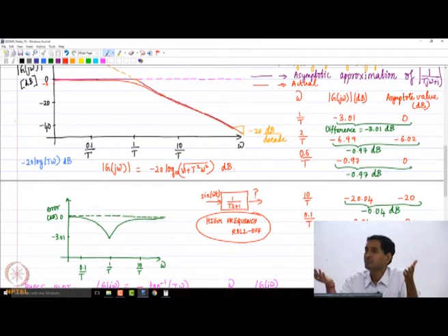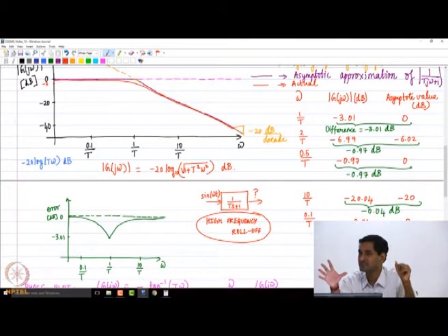So if you map this term to the transfer function of, let's say, a sensor or an actuator, which in practice you model using this first order term, which is very common by the way, if you give me the transfer function, I can immediately tell you the bandwidth. Let's say I give you a transfer function for an actuator as 1 by 0.1 s plus 1.